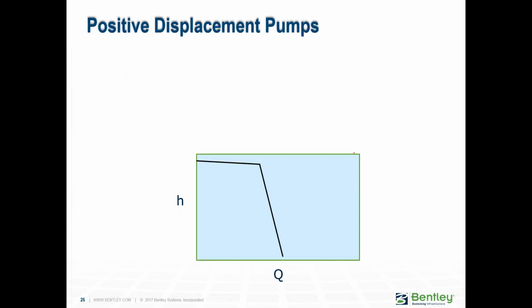There are also positive displacement pumps. I was once at WEFTEC, and I really had never seen one of these pumps before, but the guy who sold it explained it to me as like squeezing toothpaste. And really that's what it does. They're typically used for pumping solids, and because it's a mechanism pushing that toothpaste out constantly, they will pump a fixed flow regardless of the head, right? So if you have to model that, you can use what we call the multi-point curve and use a very steep slope, like what you're seeing there.